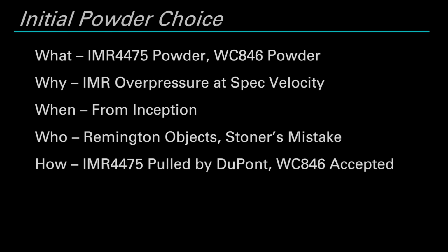On the minus side, you're generally going to be okay, but on the plus side, you can start getting yourself into trouble. In the case of 223 Remington, being 15% over nominal, when your nominal was already riding the line of the max average pressure, means that you could be as much as 15% over what that pressure limit was. This is the point whenever you start to have case failures happen, you can have primers blown out, and certainly over extended use, you might get yourself into a situation where a gun could explode.